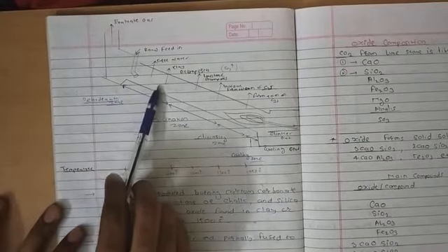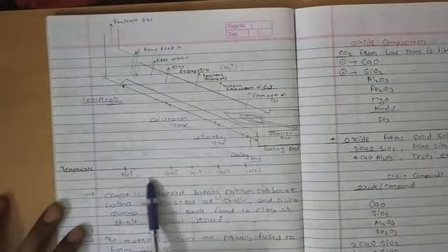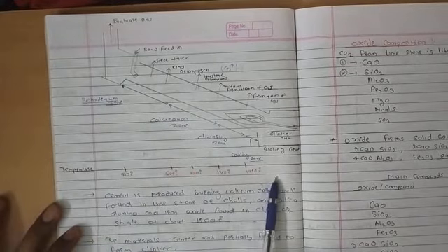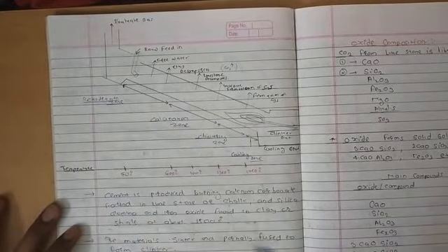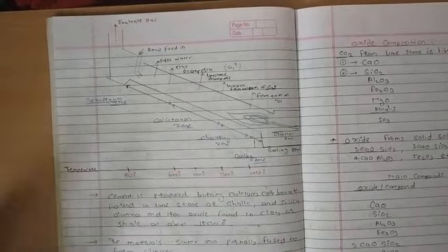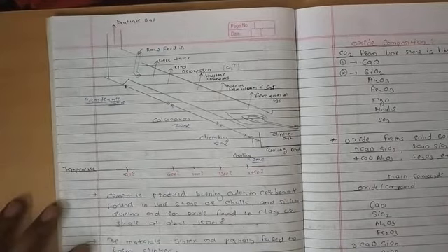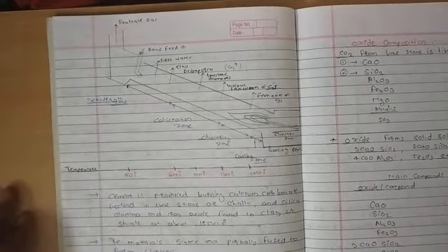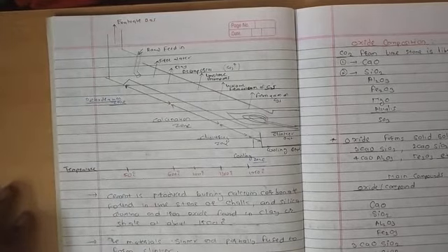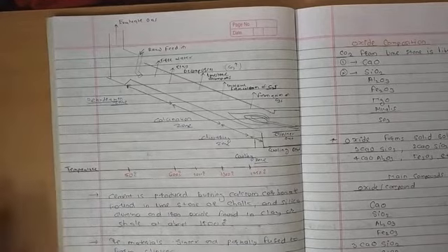As we look at this diagram, the raw feeding is here, and after that free water is evaporated. After some time the temperature also changes along this axis. With that, the decomposition of limestone happens, then formation of C3S and formation of C2S. We will look later at what C3S and C2S are. Cement is produced by burning calcium carbonate found in limestone or chalk, and silica, alumina and iron oxide found in clay and shell at about 1500 degrees Celsius.